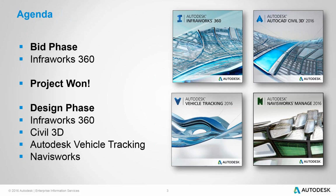In the design phase, we'll look at how you can migrate the design options from InfraWorks 360 into Civil 3D and progress through the detailed design. Use vehicle tracking to carry out swept path analysis. Then we'll see how Navisworks can be used to federate project data and carry out clash detections and construction simulation.